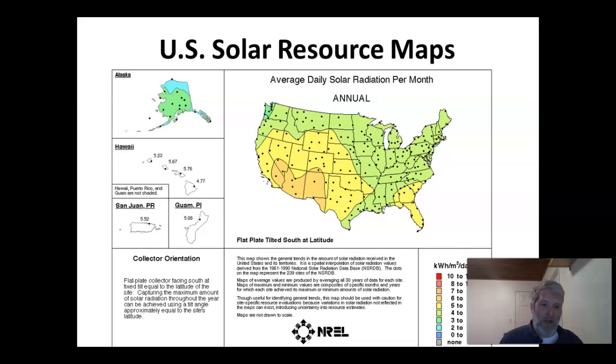So again, if we had a 10 kilowatt system and we were able to do 1 sun, that would be 10 kilowatt hours. So as long as your house was able to use 10 kilowatt hours by the time the sun came back up and was producing energy at, let's say, 8 or 9 in the morning, and it technically produces at 6, but 8 or 9 in the morning is a good metric for you. Then from when the sun goes down, let's say in the winter, it could be 5 o'clock. So from 5 p.m. to about 8 a.m., if you use less than 10 kilowatt hours, then that system will work.